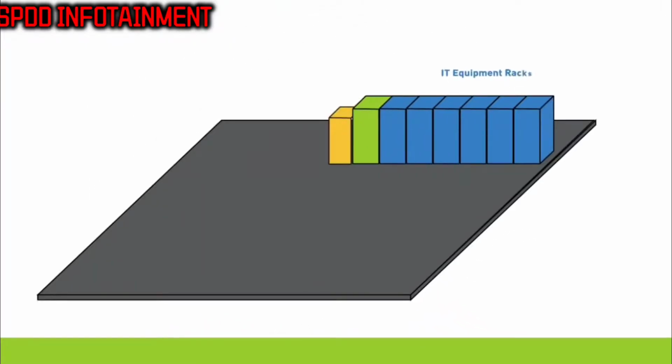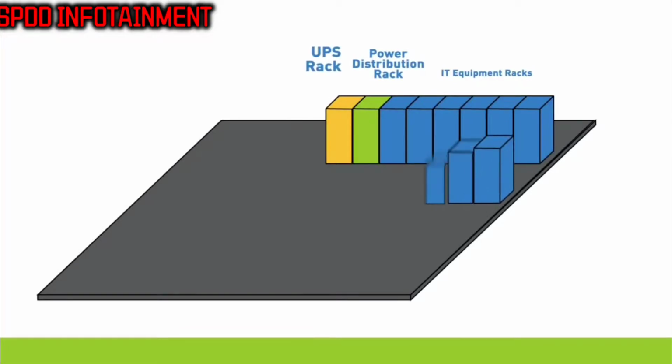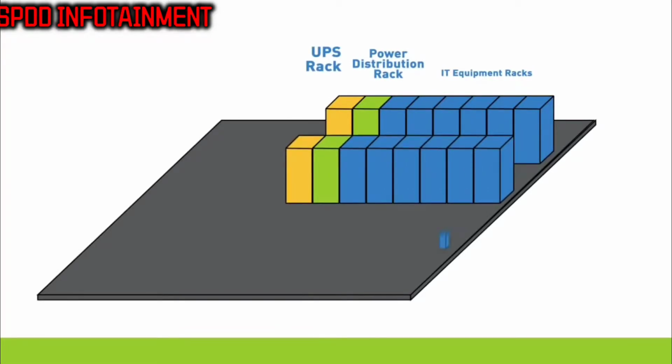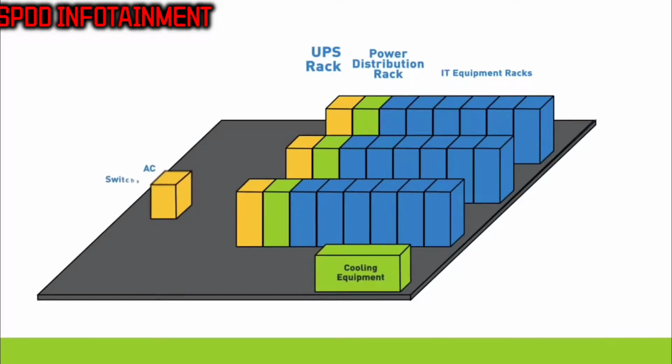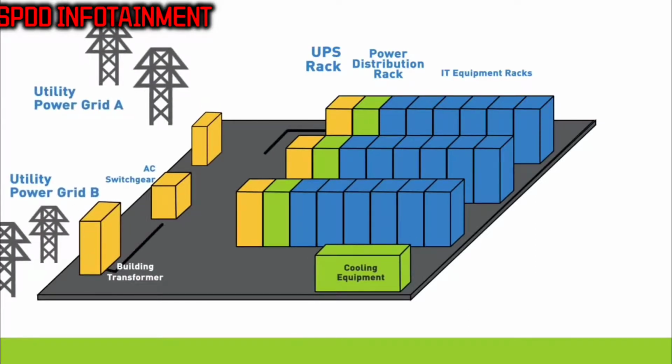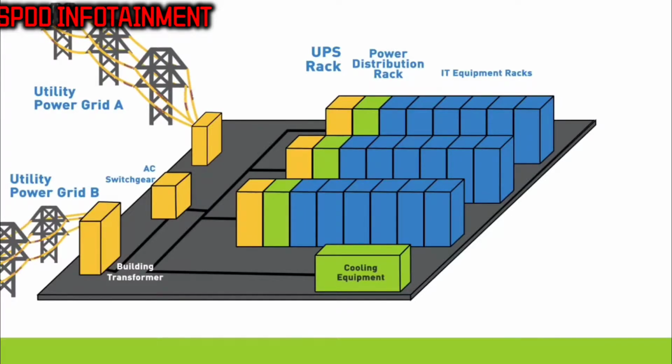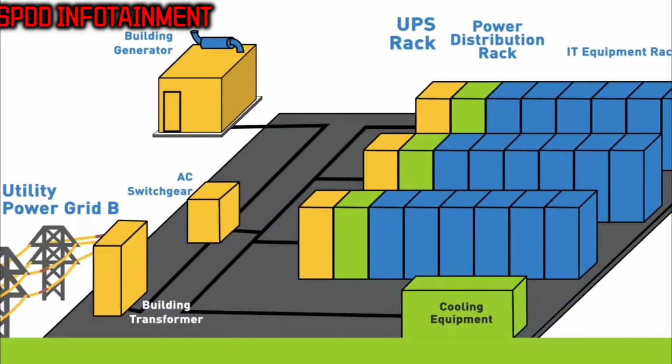To keep the discussion simple, this information will focus on North American data centers. The ideal setup for a Class 4 data center would be to have two feeds from separate utilities or from at least two main substations. This would provide two completely redundant power chains, including redundant access to the utility power grid. Since this is very expensive and usually not feasible, the most popular option is to back up the utility power feed with diesel generators. A series of switches on both the utility feed and the generator feed are used to provide a level of redundancy for all the equipment in the data center.